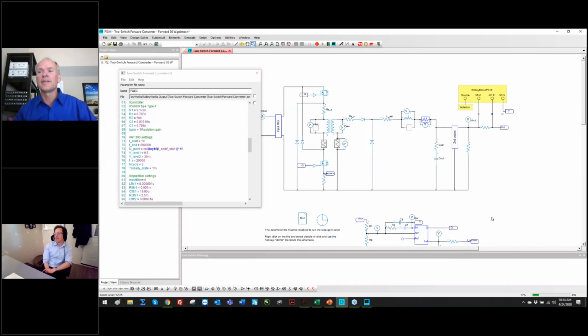Yeah. And this includes post-processing as well. One of the things that I've noticed with LTspice is if you end up with a lot of data points, it can take a little bit of time to post-process on the .measure command. Right. Whereas, right now we're sweeping at 10 hertz. Yeah. We have to process 60,000 switching cycles for 1 injected frequency, which is an enormous amount of waveform processing to do. And as it goes along, as Albert just said, PSIM is extracting the data.